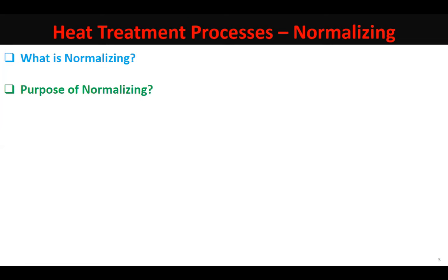You see, hardening is a very complex and a difficult process, and hardening subjects the steel components to very testing conditions. So if the steel which is being given hardening heat treatment does not have a good microstructure in the beginning, if the steel which is being hardened has got improper grain size, or it has a lot of internal stresses in it, or it has some other problems, and it is straight away subjected to hardening, the steel would fail during the hardening process only.